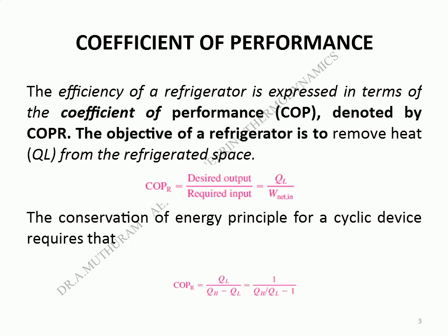Coefficient of performance. The efficiency of a refrigerator is expressed in terms of the coefficient of performance, denoted by COP_R. The objective of a refrigerator is to remove heat Q_L from the refrigerated space. The COP of a refrigerator is the ratio of desired output to the required input. The conservation of energy principle for a cyclic device requires that COP equals